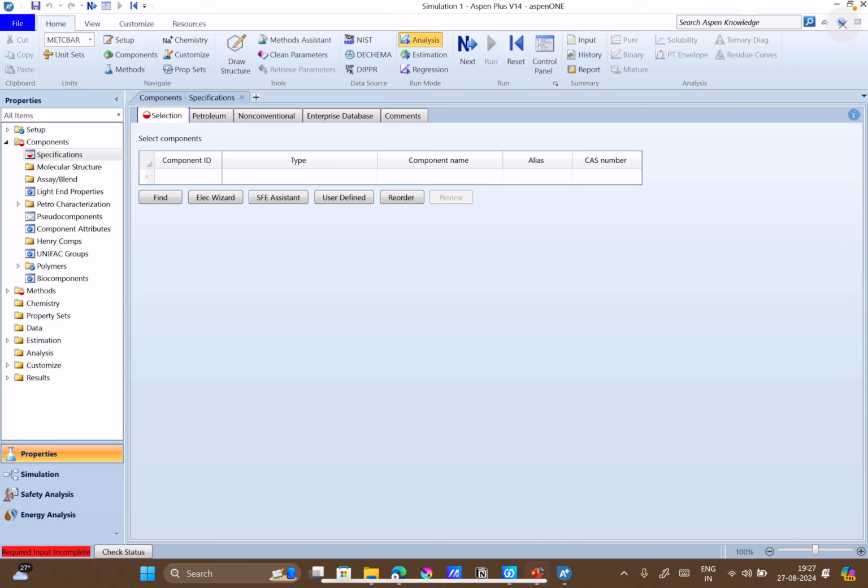When you press OK, this data will be added, and you can see in the data section here this data has been created, and you can find other information about the data. From here you can plot the data itself, like TXY diagram. Sorry, not TXY, since it's isothermal data, we want to do PXY diagram. So this is the PXY diagram from experiment at 334 Kelvin.